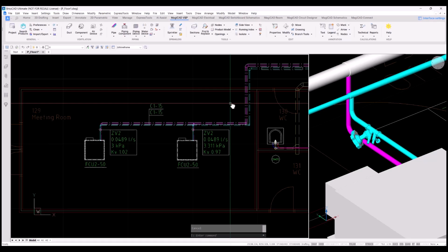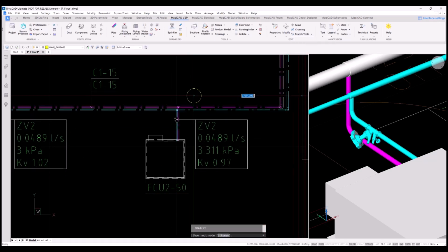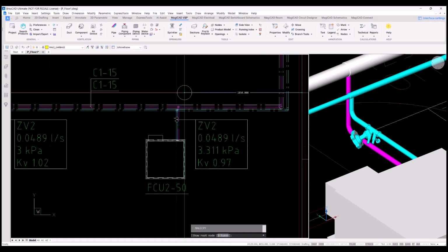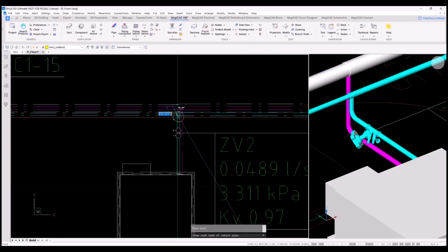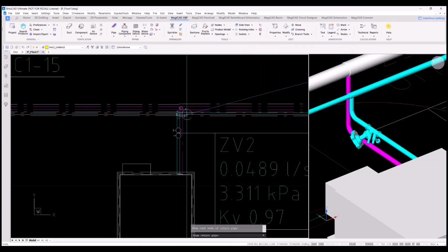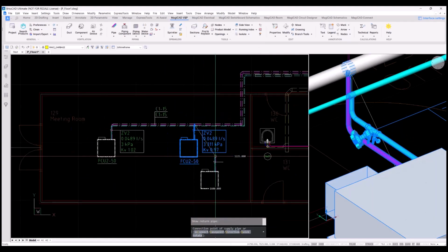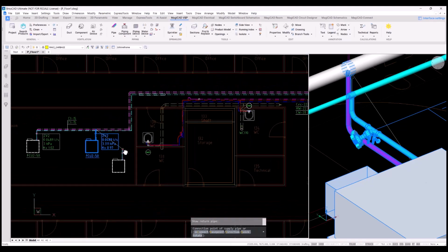And another tool that speeds up the design process is the copy branch. So let's say we have here a ready-made branch with a device, with a valve and dimension texts. So therefore, with this copy branch, we can take all of them at once and install it somewhere else as such. We include the T branches and the connecting pipes. There now all the segments, fittings, valves, and dimension texts follow along.